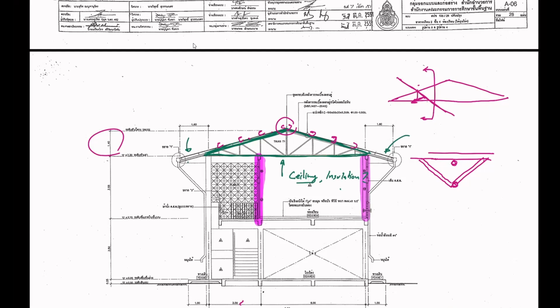You are no longer dealing with a pure theoretical truss. You are dealing with a frame now, pretty much like structural analysis #2. All the members in your so-called truss will have both axial force and bending moment.